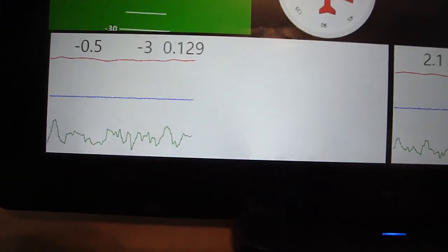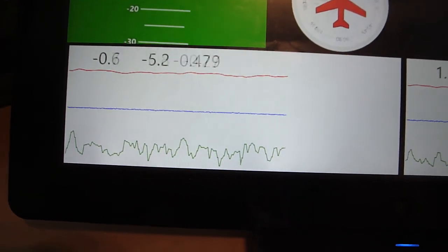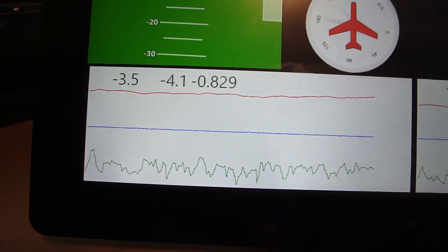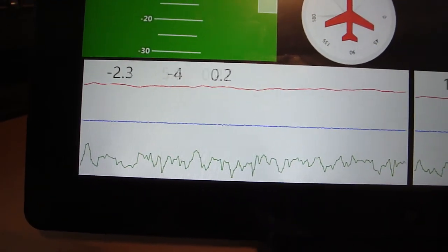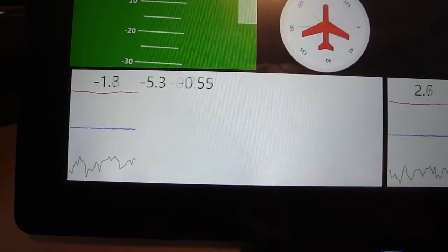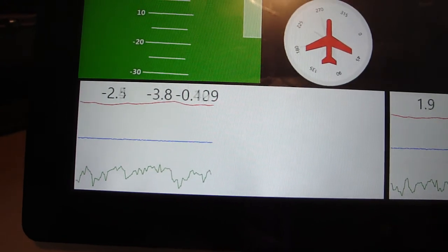You can see we're getting a lot of noise in the accelerometer on the bottom, and I'm not sure if that's from vibrations or from electrical. I haven't sorted that out yet, but hopefully we'll get something figured out on that. But what we've done with software is, using a complementary filter, combine the output from the accelerometer and the gyrometer to give us something that's somewhat consistent for the angle up there.